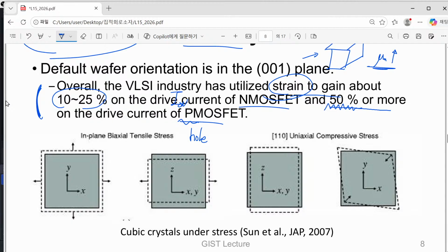In order to compensate for that difference, we have to introduce a wider PMOSFET. If you remember correctly, the typical value we studied in our previous course is 2 to 1. So our PMOSFET should be approximately twice as wide to match the drive current.